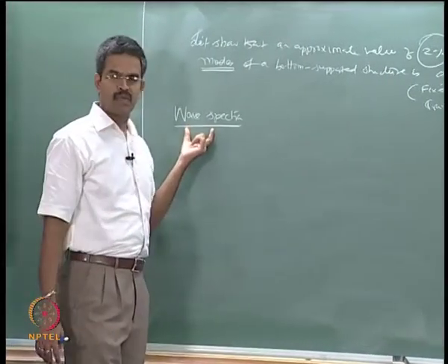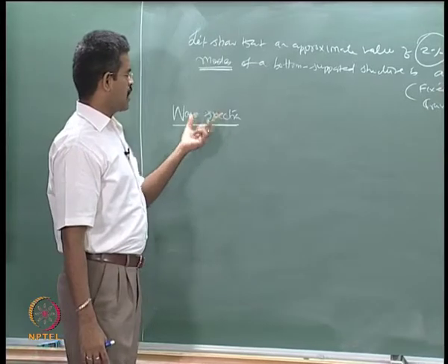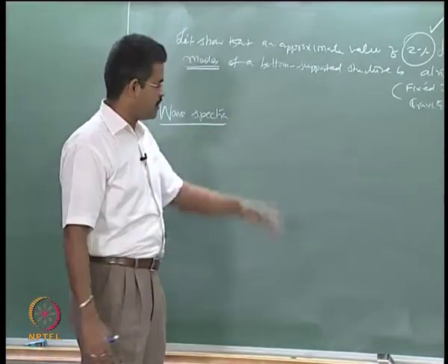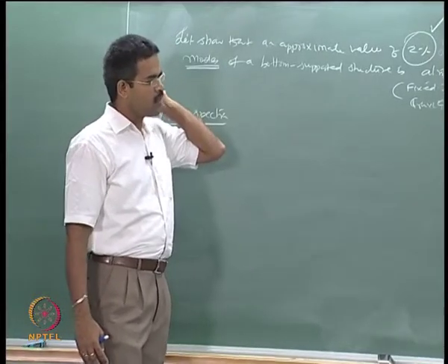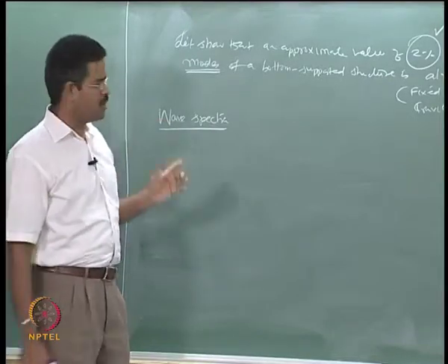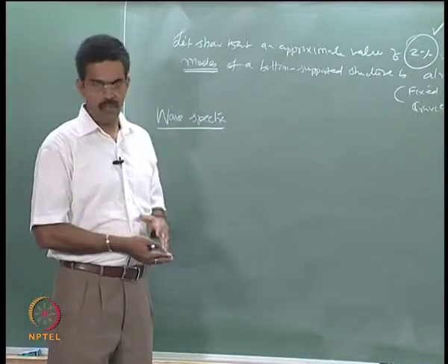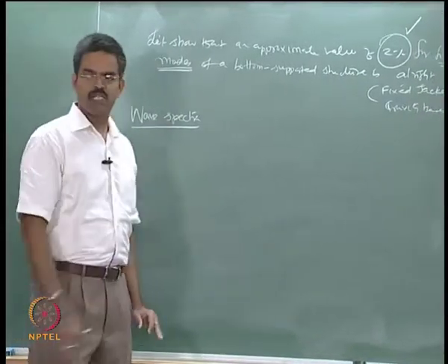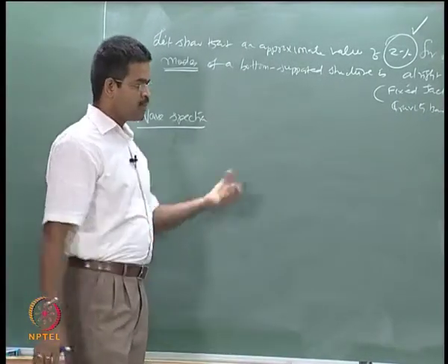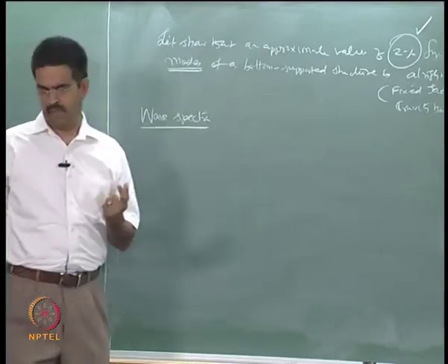So, we will talk about wave spectra now. There is a lot of confusion around wave spectra, there are different spectra recommended by literature, and we will quickly see all of them because this lecture is not focusing on the hydrodynamic aspects of deriving the wave spectra. We are only looking from the designer's perspective at which wave spectra I should use for design of marine structures, why I should use it, and what are the important critical points of the respective wave spectra.